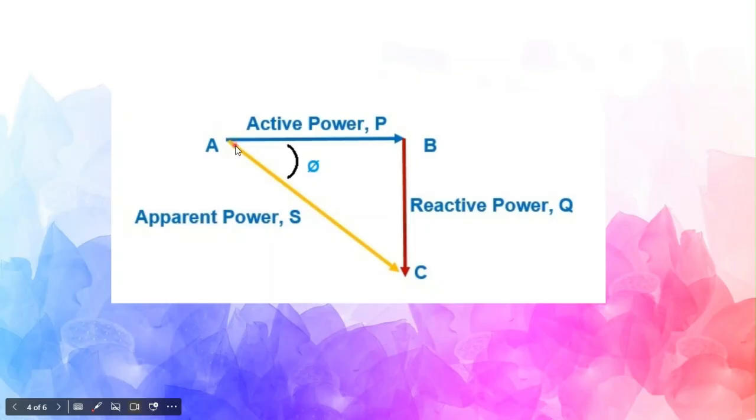Transformers and generators are all rated with KVA because we don't know the loads which are to be driven by the transformer or the generator. If the loads are lagging loads, inductive loads, then in that case a high KVA rating is required, a higher transformer size is required. But if we can mitigate that, then we can reduce the transformer size up to this only. That is the advantage we can get.